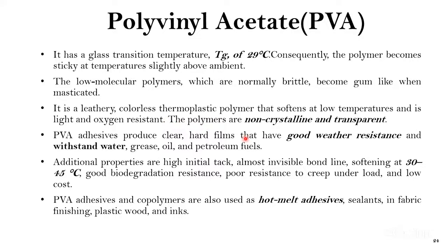And this polymer, as I told, is atactic in nature and amorphous. That is the reason these polymers are non-crystalline and have a larger portion of amorphous content. That's why they are transparent in nature.